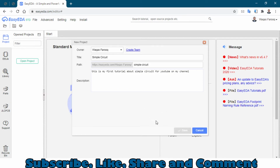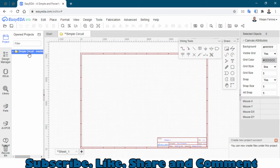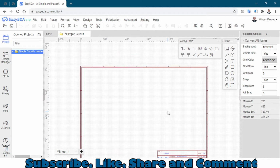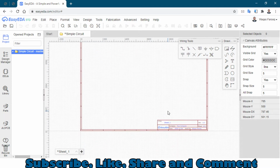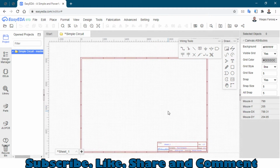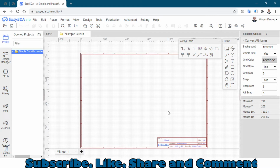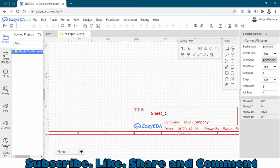When you save it and it's successfully done, you will see here, as you can see, simple circuit, and you will get this file. This is the sheet where you will be working. If I want to zoom in, you cannot just rotate the mouse wheel to zoom in and zoom out. When you rotate it, the sheet will go up and down. So in order to zoom, you have to press Ctrl and then rotate the wheel. You will be able to zoom.